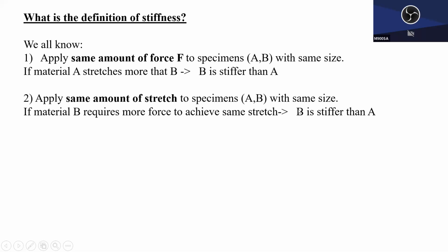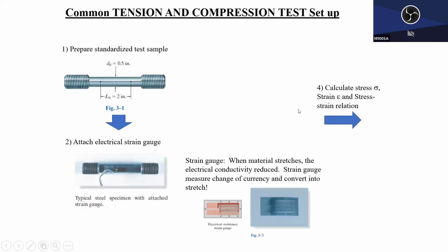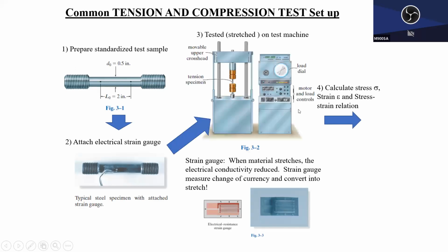But we are engineers and now we know stress and strain, so we can come up with a more scientific way to measure it. What we usually do is create the so-called doggy bone sample. It looks like a dog bone, right? Many people call it a doggy bone sample too. It is created so that the tester can grab both ends firmly.